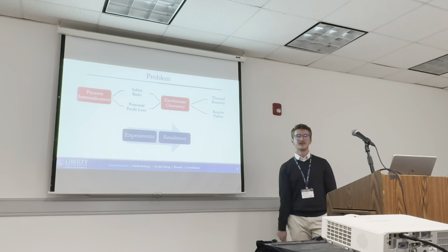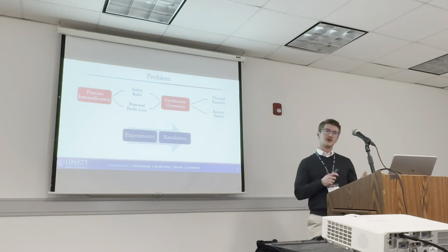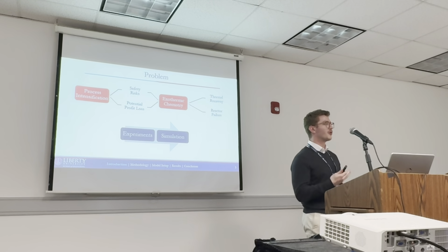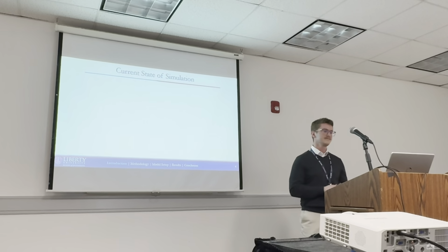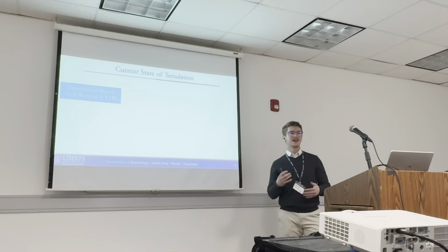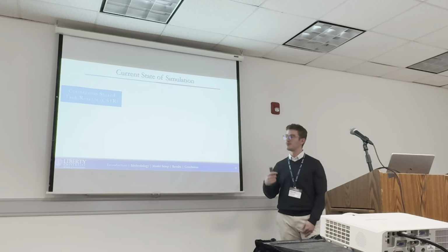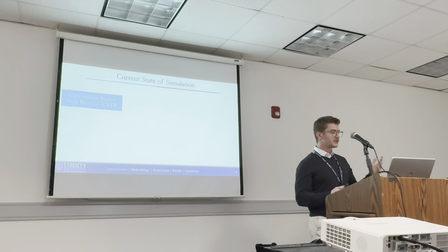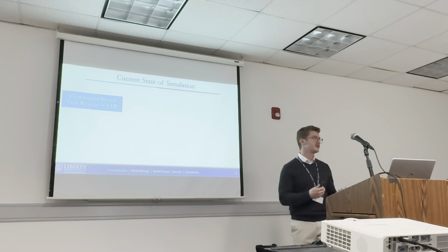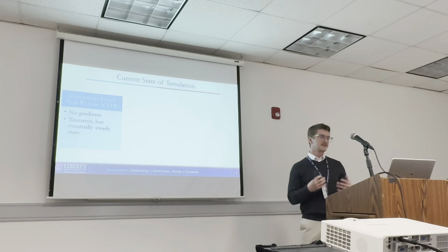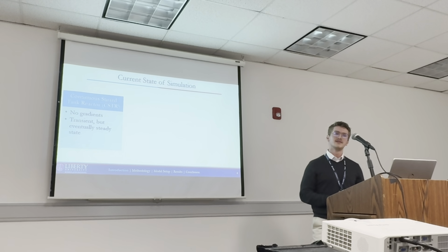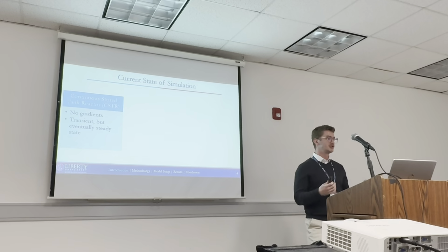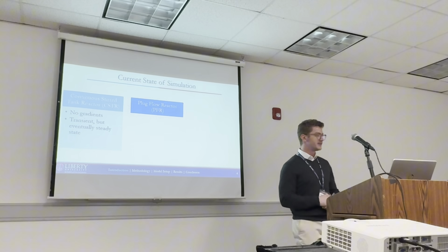And so for these reasons, simulation is often preferred for polymerization systems as opposed to experiments when trying to learn more about those systems. Because of that, there's a lot of simulations specific to polymers. They all fall into 3 kind of classes. The first of which is a continuous stirred tank reactor, or CSTR. And this is characterized by no internal gradients or a perfectly mixed reactor, and is transient, but will eventually reach a kind of quasi-steady state.